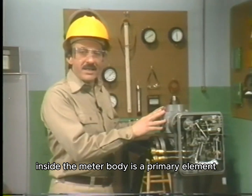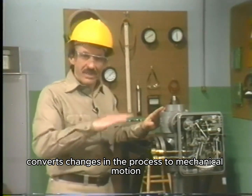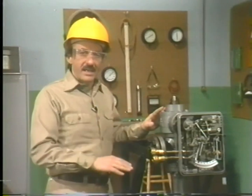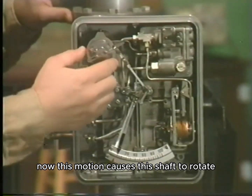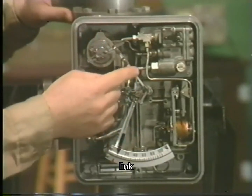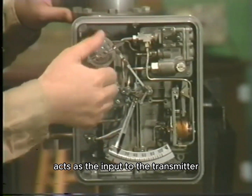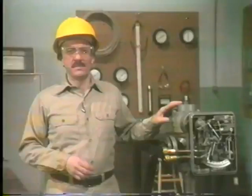Inside the meter body is a primary element, which converts changes in the process to mechanical motion. This motion causes this shaft to rotate, and the shaft is connected to the transmitter by this link so that the rotating motion acts as the input to the transmitter.